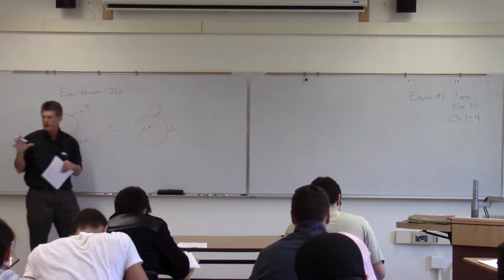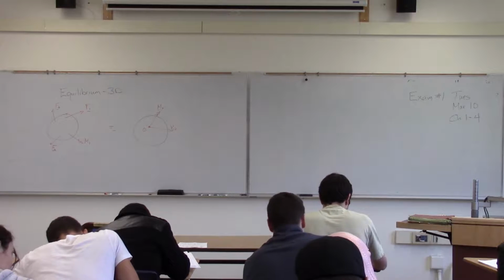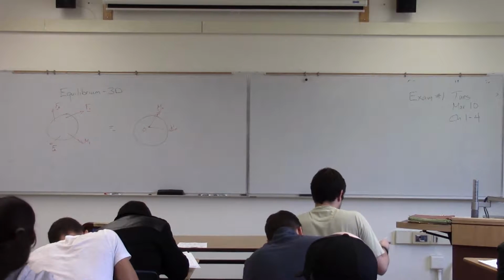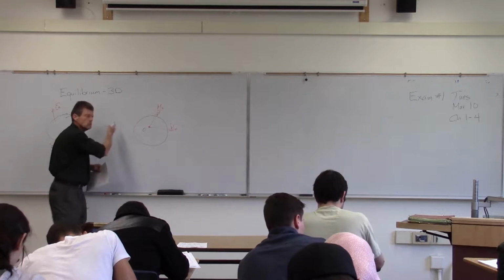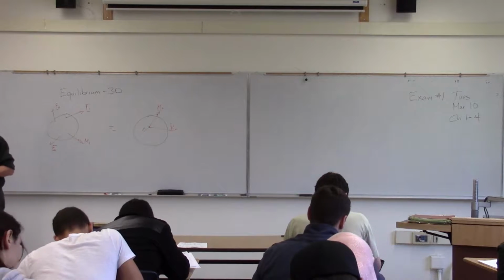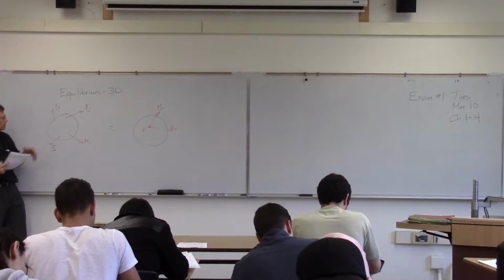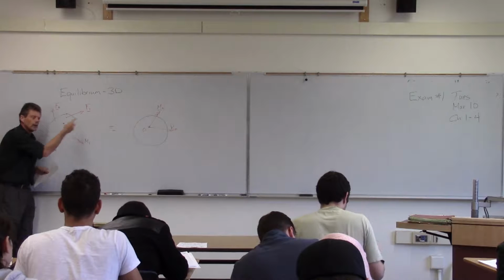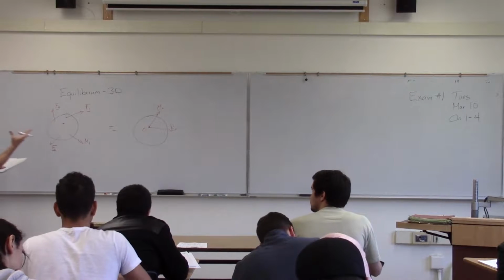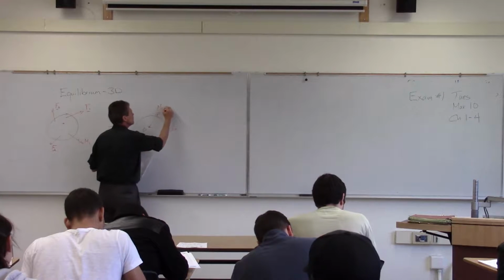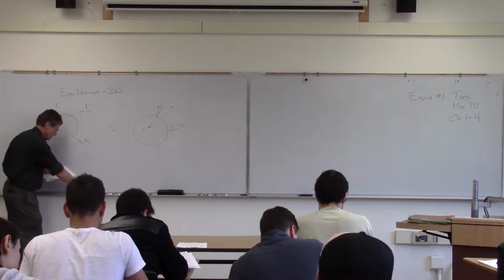And what we found, when we went through all of this 3D stuff, was taking these forces and walking them out the door to a point, moving them out of their line of action, which created a couple. Then we can bring this free couple along, take it to this point O, and what we find is that we can create a resultant couple and a resultant force. Now the key thing is, when we go there, we're going to set those two equal to 0. Nothing fancy.